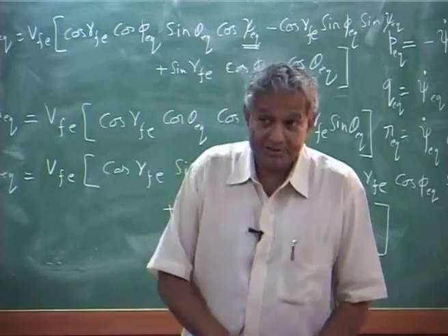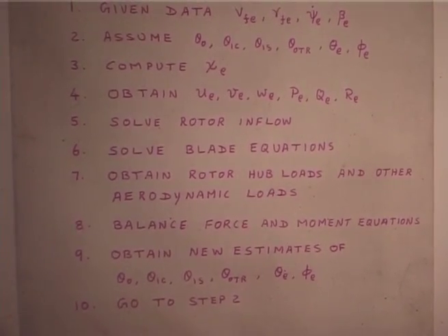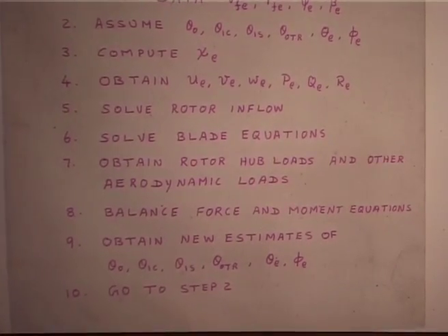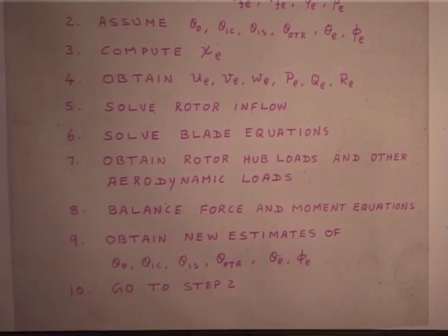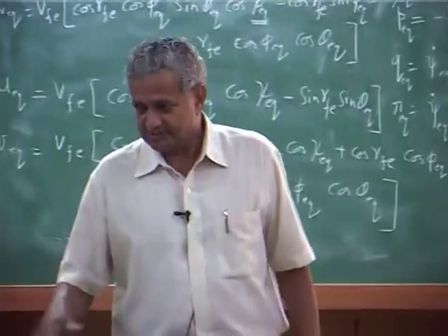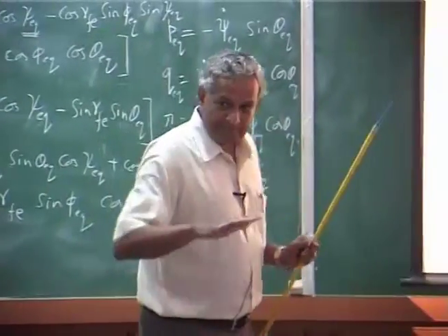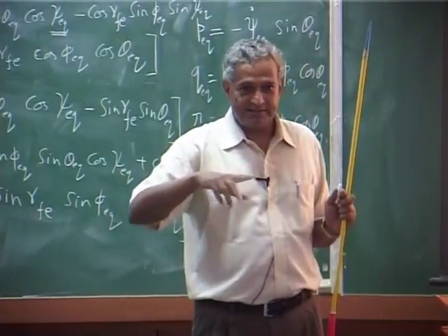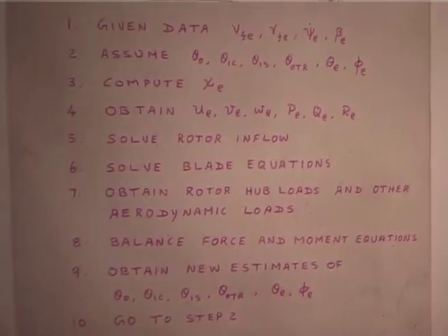And this is where in between you have to get the rotor inflow, please understand. This is also equally complicated problem, because rotor inflow is related to rotor thrust. Okay. So, you can have various types of inflow models, dynamic wake model, and we have incorporated Dries model you can put, but that is again a constant, even though it varies along the radial and azimuth, it does not vary with time.